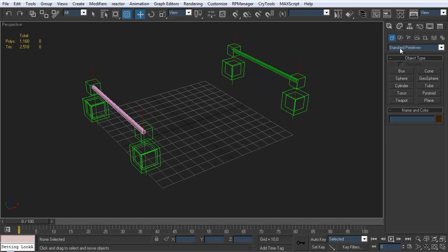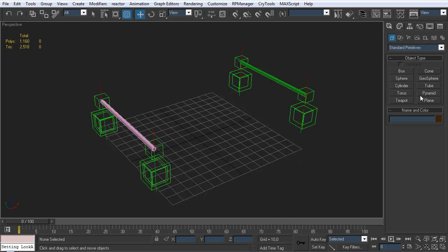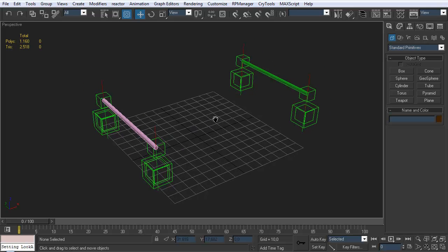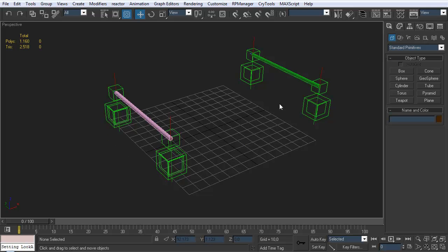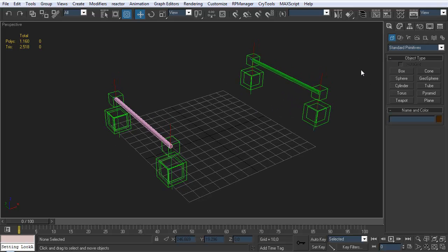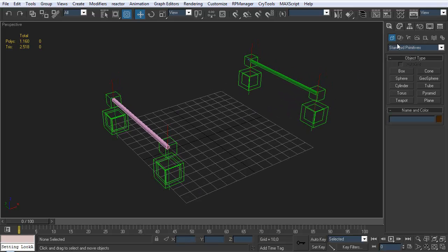For that we will need to create a new dummy, but another thing you can't forget is renaming these to line axle front. And this one, line axle rear. Always make sure to name your components correctly, because as you noticed when using the expressions, it's hard to find objects you haven't named correctly.